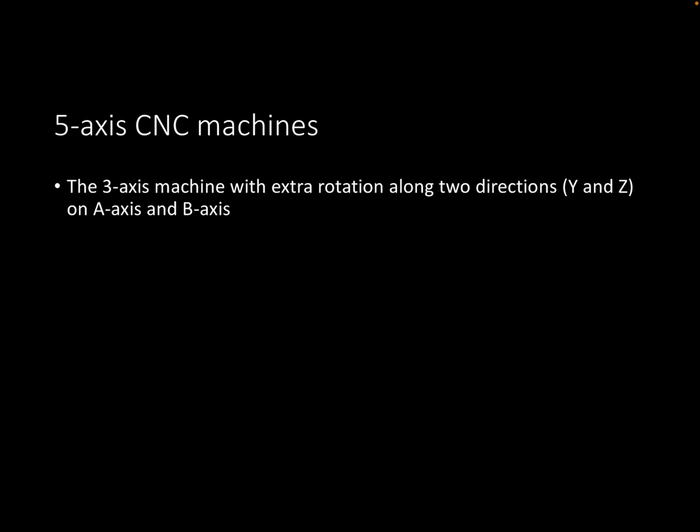So that is basically the 5-axis CNC machines where you can create complicated parts like artificial bones, because that will allow the motion of the tool in undercut areas or access to undercuts and deep holes. So in such a way you can create parts having complicated geometries.